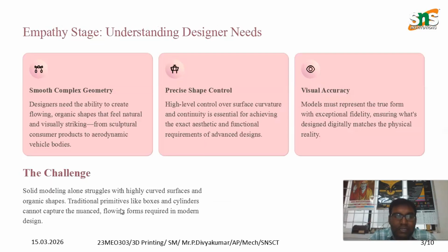There are about three types of surfaces: planar surface, curved surface, ruled surface. In case of planar surface, it is a flat structure, example the table top. In case of curved surface, it has a smooth curved shape for the particular type of object. Example of the curved surface is the car body. It is majorly used in automobile industries. In case of ruled surface, it is formed by moving a straight line between two curves.